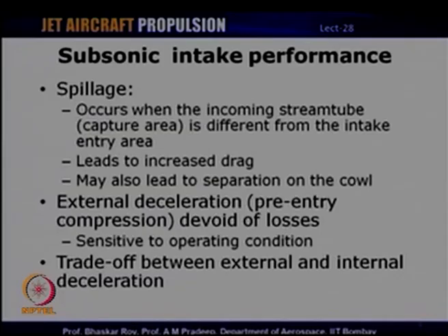So, the designer has to carry out a trade off between internal and external deceleration, depending upon the design condition of the intake, which is usually during cruise of the aircraft, when the aircraft operates for the maximum duration.